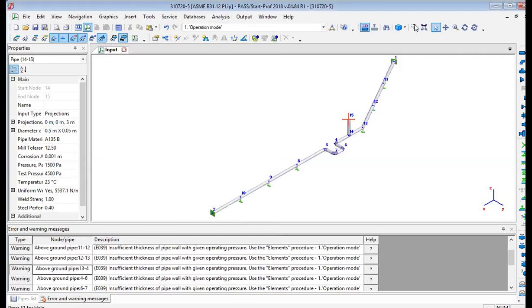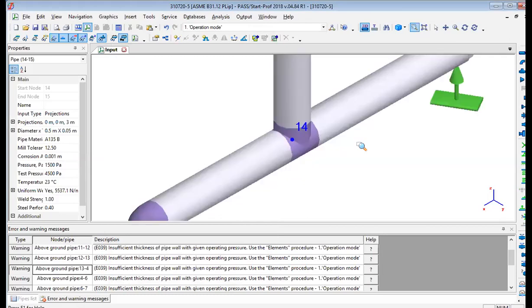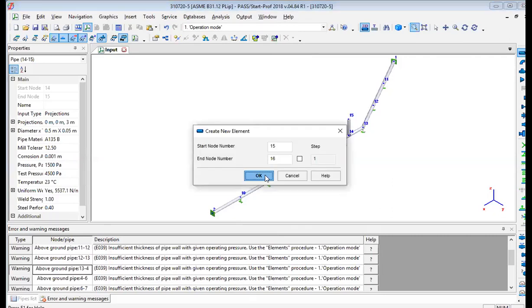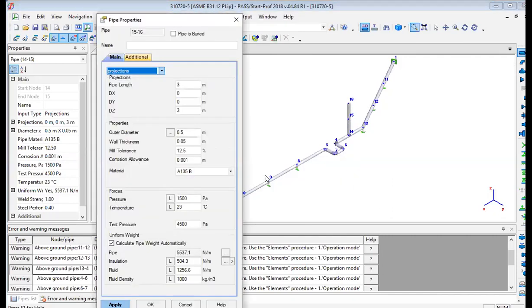All right, if you zoom in, so can you see your T? So we go back to fit to screen. Then from here we'll continue the piping 15 to 16. Yes. What direction do I want to go? Do I want to go Y again and Z again? No. Z, X, yes. Positive or negative X? This time we are going negative X. Not even X. You want to mislead me. It's Y. So minus 5.